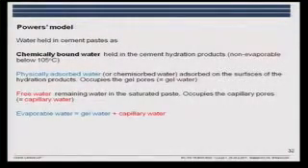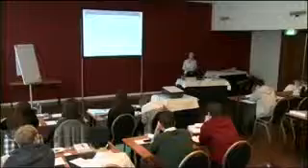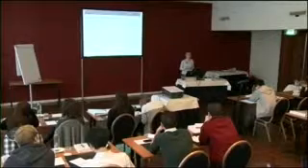And the evaporable water, meaning the water which was lost until 105 degrees Celsius, that was the gel water and the capillary water. And here you see that the model is based on a huge amount of experimental work.